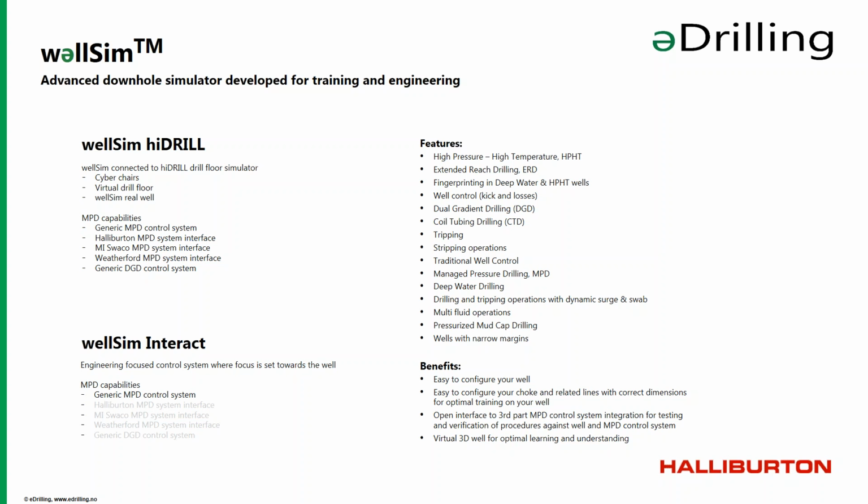If you look at the features of the WellSim products, we have used them a lot for HPHT, ERD, well control, dual gradient drilling, coiled tubing drilling, and so on. The benefit of using one of these simulators together with MPD operation is that it's very easy to configure the real well in the simulator, so you can prepare the crew for the MPD operation on the actual well.